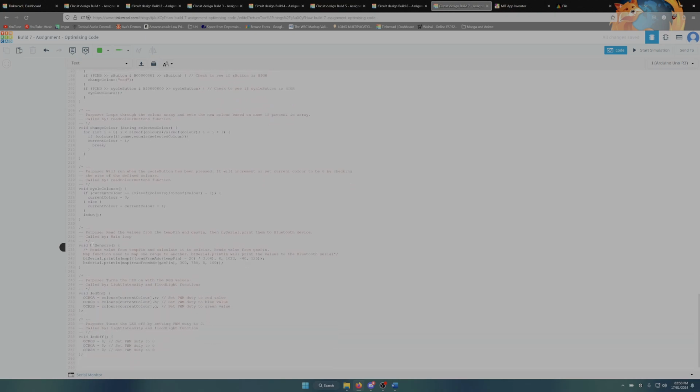Continuing down, the BT sensor has also been changed, so it's now using this read from ADC function to get the value, just to get rid of analog read, and it's put straight into the print function. The same with the gas readings.